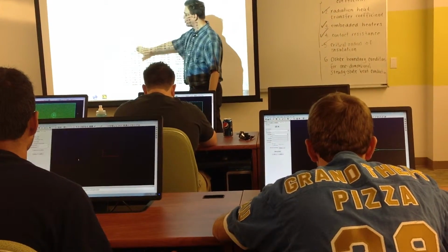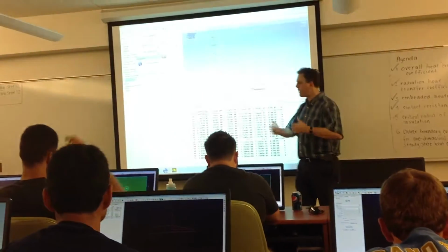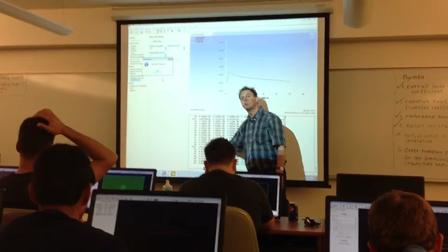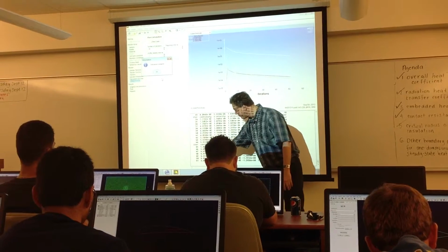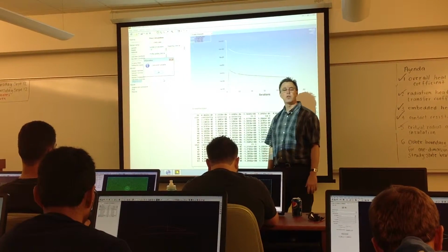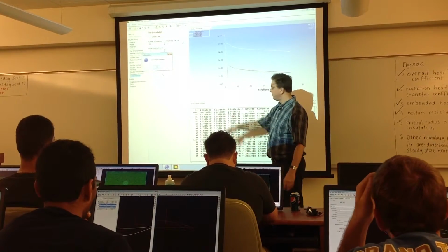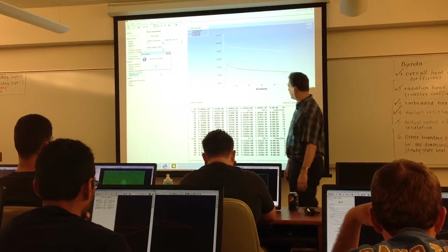So as this goes towards 0, that means that the solution is completely steady. There's no imbalance of mass at all. If this column drives towards 0, it started off at 1. It's already at 0.038. So it's only got 4% of the unsteadiness that it started with, which is a good sign. The X velocity, Y velocity are already down to really small numbers.